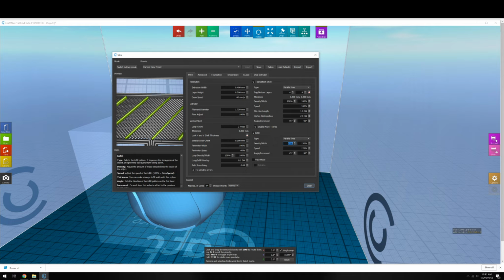It is rare to see an advantage of going over 50% infill, as by that point, the lines become very small and very intertwined. If you're finding that your print is taking too long, this is one of the first things you should look at and decide whether or not you need to run as thick of density as you are. The next line is the speed, which again you shouldn't need to change, and the angle increment changes how aggressively you want these lines to cross.